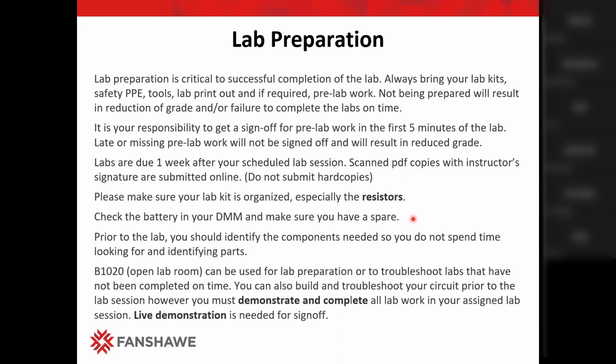And please, please, please do not put the alligator clips into the power supply banana female connectors. Alligator clips do damage those connectors from inside, and they have to be replaced. Because it's a school and this equipment is heavily used by many, many people, if everybody's using alligator clips in those banana jacks, then Perry wouldn't have time to do anything else. He would just be replacing those. So, all right. Prior to the lab, you should identify the components needed.